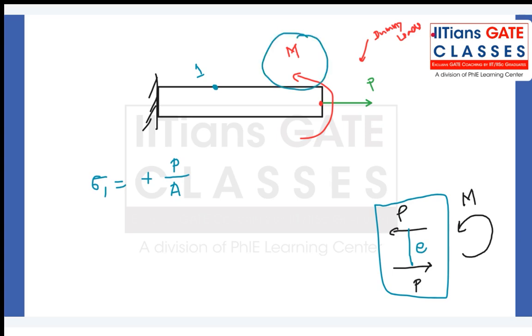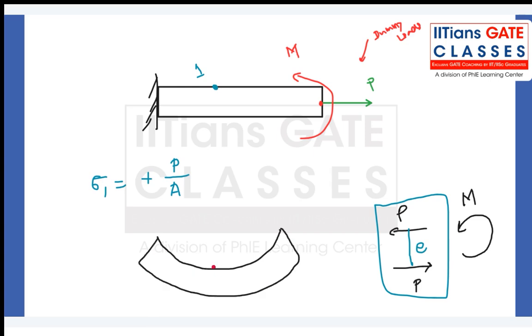And this is what is known as bending. We have an entire lecture on this, and I'm just giving you a glimpse here. Now, when the bending happens, this is known as sagging. It will bend this way, and when it bends this way, the stress at this point will be minus M by Z, where M is the bending moment and Z is the section modulus.